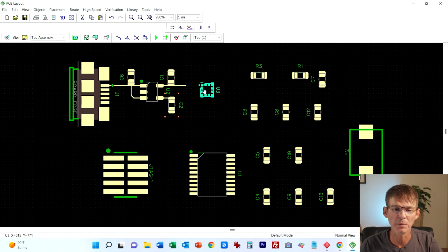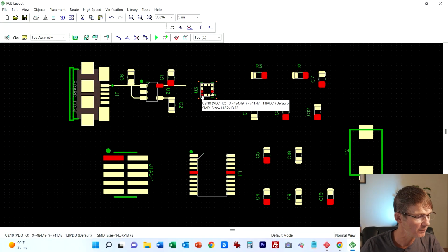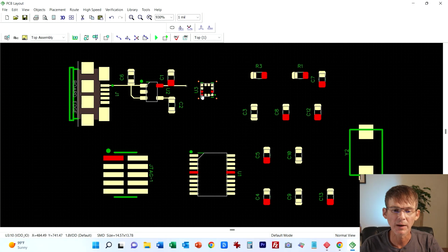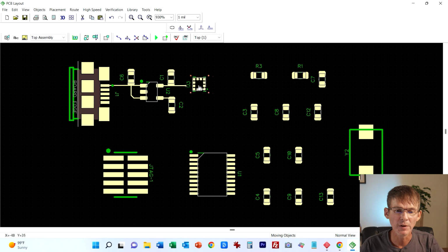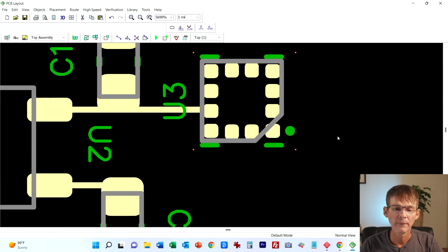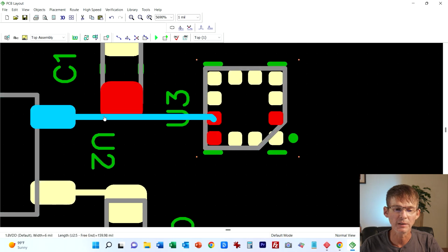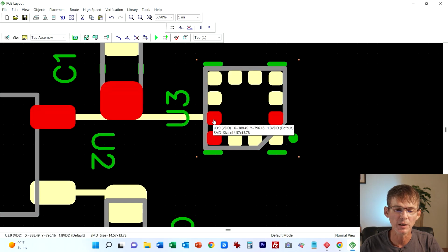So it doesn't really matter. We can route that anyways. But these two lines here, these are the main input supplies. So let's just rotate this around so that those are better placed. Yeah, like this, okay? Then we can just essentially move this up, and let me zoom in here so I can see what I'm doing. There, so you can see now we have a trace. This is coming out of the linear regulator and going into the input pin, the VDD pin for the accelerometer.